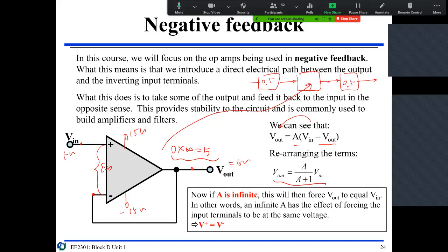Because in and out, this block is 1. In and out are the same, V out equals V in. So in this case, this answer is, have peace of mind, please, this guy times this guy, it's 0.25. Because of this amplifier, it will make your input impedance matched.